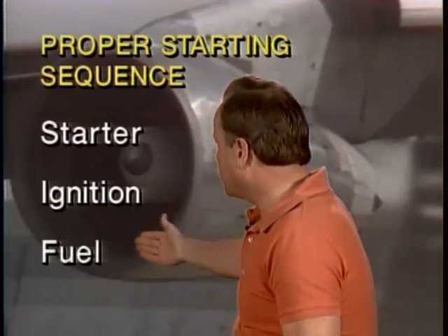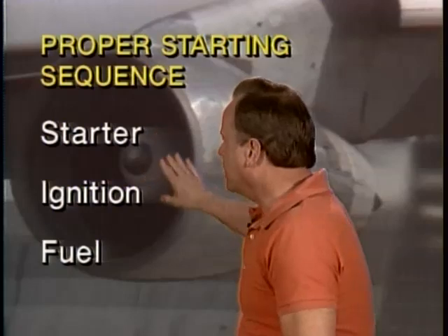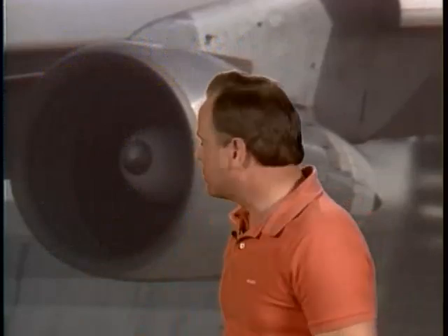The reason the fuel is last is you want to make sure that you have everything else going. Proper air, ignition, then the fuel. That way you're avoiding a hot start. Now, what is a hot start? Well, a hot start is if you have exhaust gas temperature go too high.